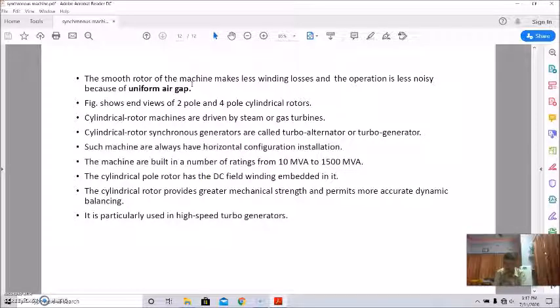The insulation of the 2 relatively low voltage slip rings from the shaft can be provided easily, whereas if the generated output is taken from the rotating part, the insulation will be more complicated and costly. The bulk and weight of the armature windings are substantially greater than those of the field poles, so the size of the machine is reduced. If the bulk portion were under rotation, there is a possibility that due to great centrifugal force, some damage may happen.